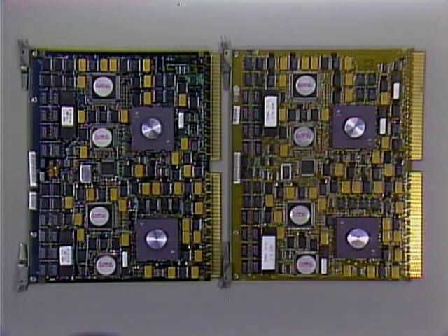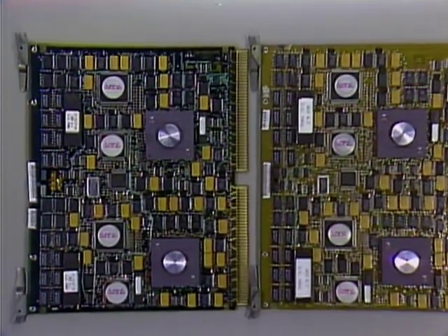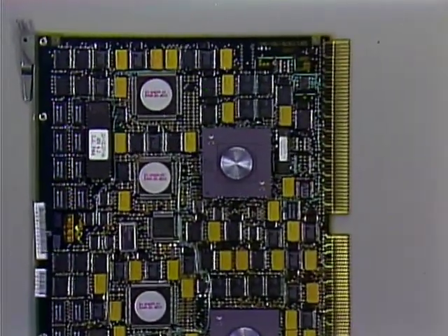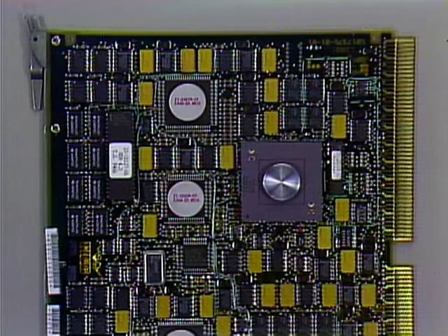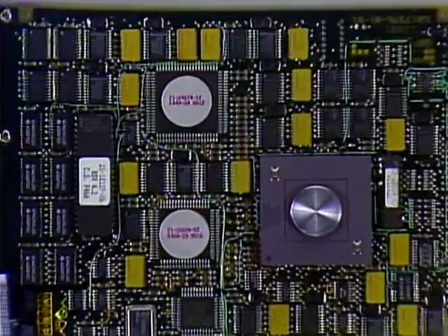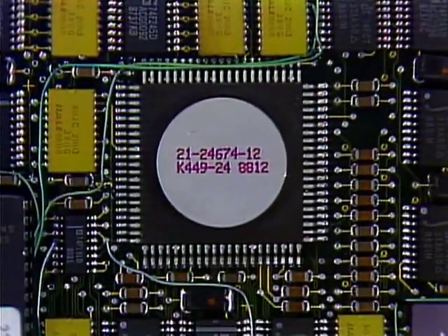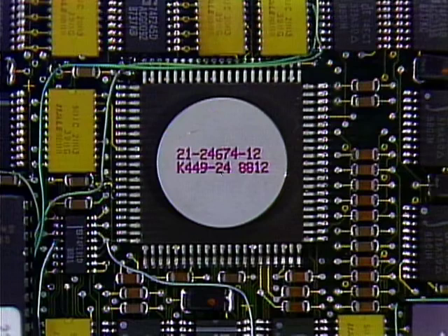Because of the symmetry of the KA60, the functionality of processor A is the same as that of processor B. We will discuss one processor in this lesson, but the information is applicable to either processor. The KA60 CPU module uses the same CVAX CPU chip that is currently used in Microvax 3500-3600 series systems. The CVAX chip incorporates all standard VAX features.